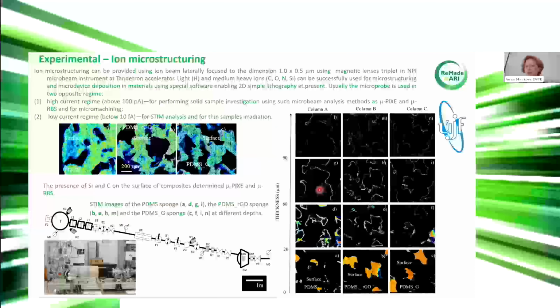Now we would like to know more about the internal structure, and we employed XRD. In this case, we found out in the XRD that this material is polycrystalline, and we can identify in this column, this nanopillar, so-called basal domains and vertical domains.